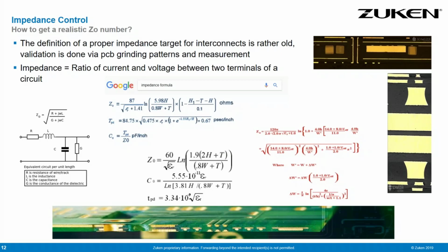That's not something modeled in these formulas. And last but not least, these formulas typically assume a trace is more or less alone on a printed circuit board, so they model single-ended traces. They cannot model coupled structures well. I don't know any really good formulas addressing differential traces, nor any formula modeling crosstalk situations. So coupled traces cannot be modeled by formulas. Here, more sophisticated mathematical methods like field solvers have to come into place to address proper characteristic impedance figures.